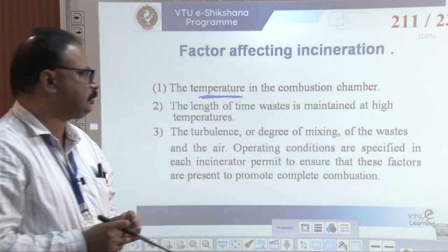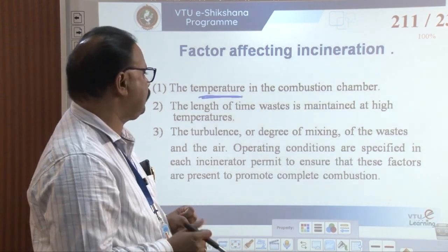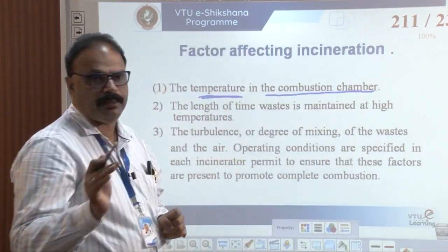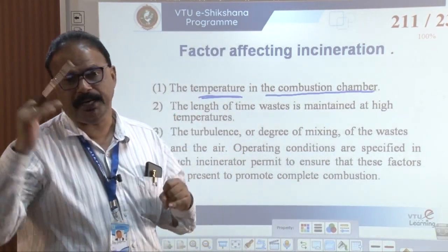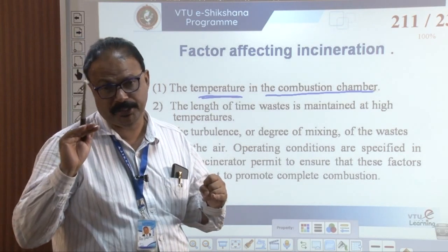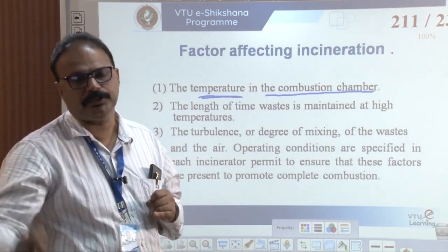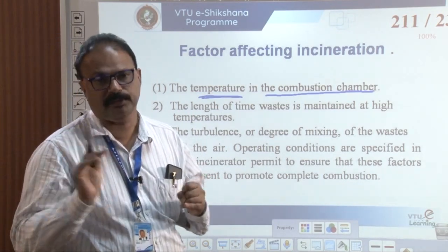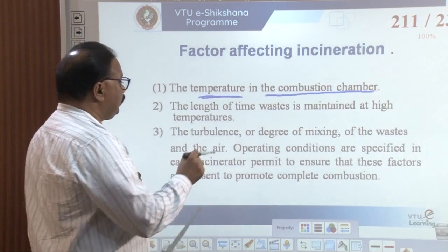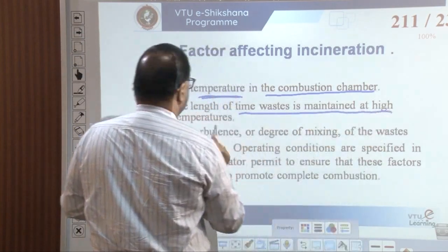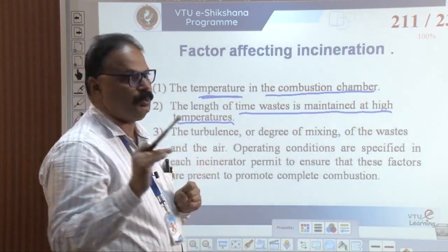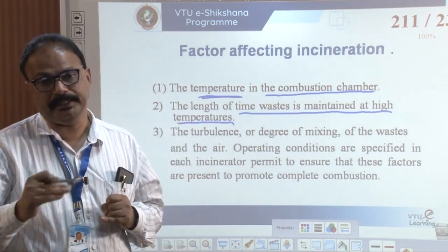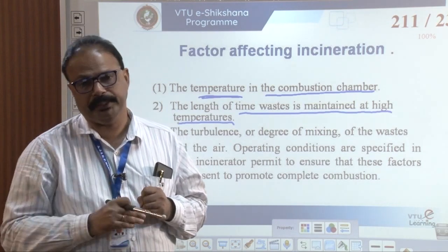First is the temperature, the high temperature of the combustion chamber. We have to maintain that factor affecting the incineration. Otherwise, the chamber may burn or clogging may take place, with melting of the grate. Time: length of the time waste is maintained at a high temperature. It should not take more time for burning.